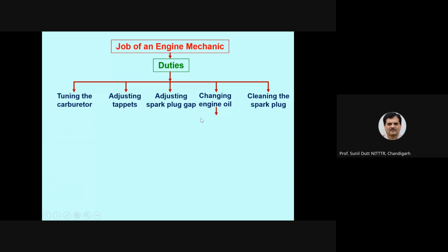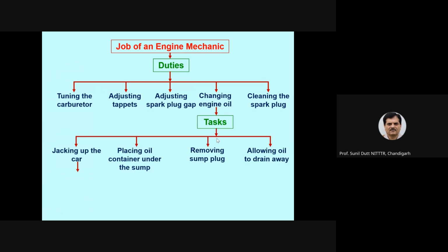Now let us focus on one: changing engine oil. For this, the tasks required are: firstly, jacking up the car. This is a must. Then you need to place the oil container under the sump, remove the sump plug, and then allow the oil to drain away. Now, these can be further broken down.